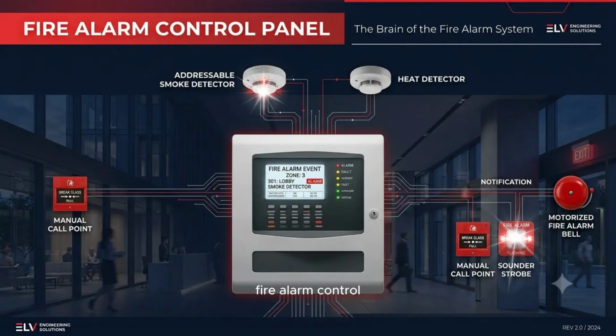1. Fire alarm control. We have the fire alarm control panel, or FACP. This is the main control unit, or we can say it is the brain of the fire alarm system. All detection devices and input-output modules are connected to the fire alarm control panel. The panel continuously monitors the system and receives signals from devices such as smoke detectors, heat detectors, manual call points, and other monitoring devices. When a detector senses a fire condition, it sends a signal to the control panel. The panel then processes the signal and activates the programmed outputs. For example, it can activate sounders, strobes, fire alarm bells, voice evacuation systems, and other fire protection equipment.